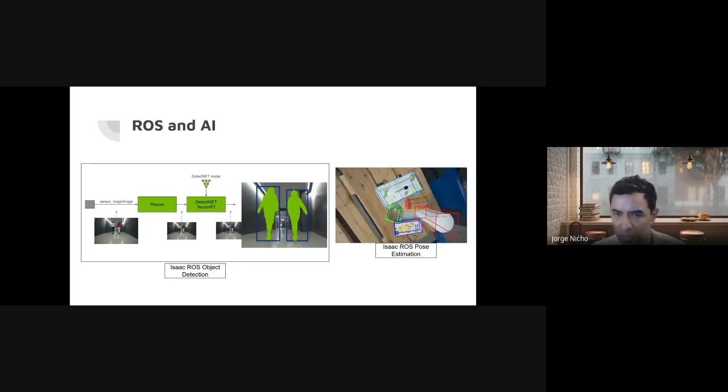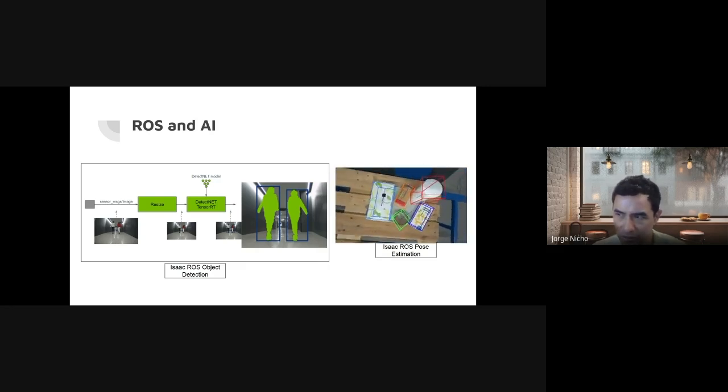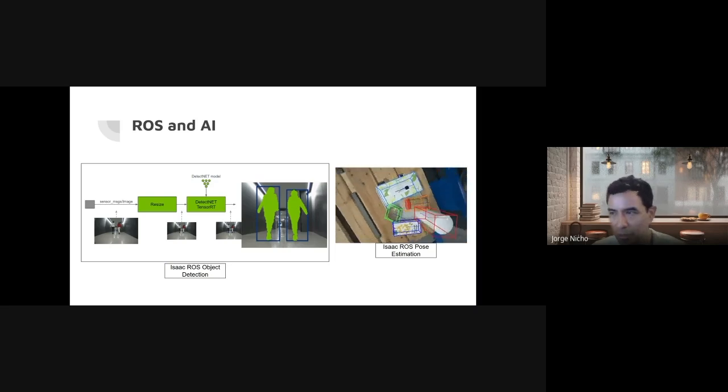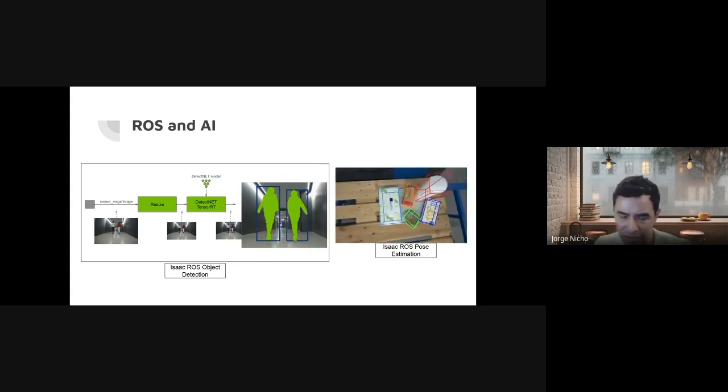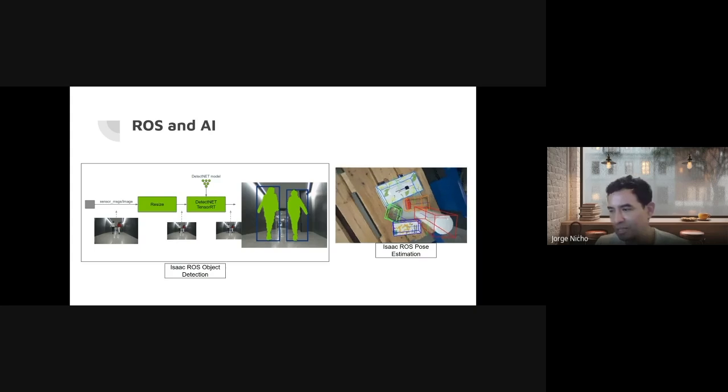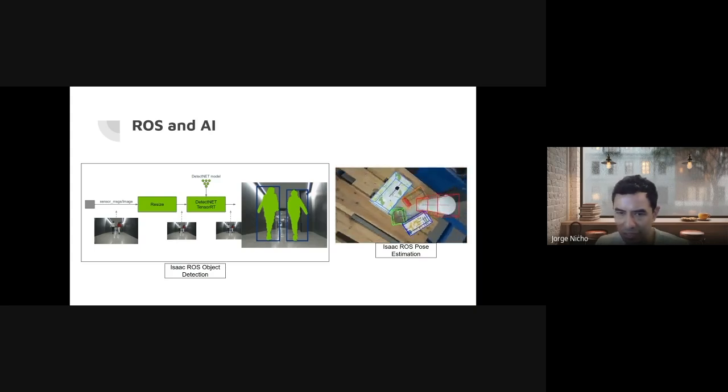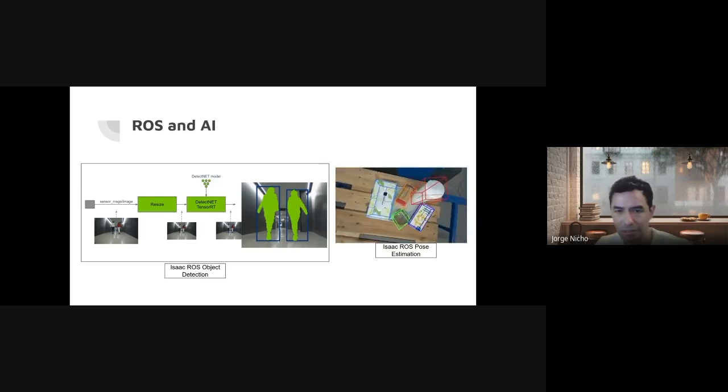So depending on what you're doing, you kind of have to do your own research on the degree of support that you'll get if you use ROS, right? But I would say even if there's no ROS support, a lot of it you can do in ROS, like all of the reasoning, all of the logic. It's still far easier to do in ROS. And then at the end, you would just write a translation layer that takes whatever output ROS gives you, and then translate it into what the robot wants.